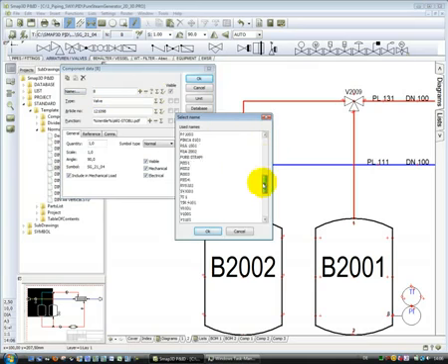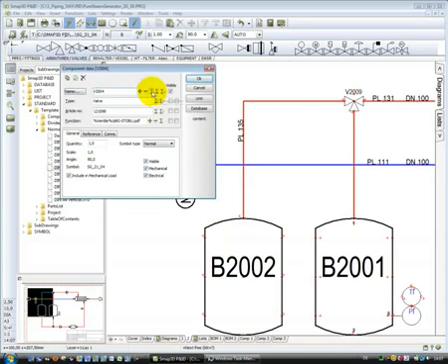And if he would like to have a totally different tag number, then I select a kind of tag number from the used names. Using the next free functionality, the software automatically counts up to the next free number. And I'm not able to make mistakes by counting or creating two different components with the same tag number.